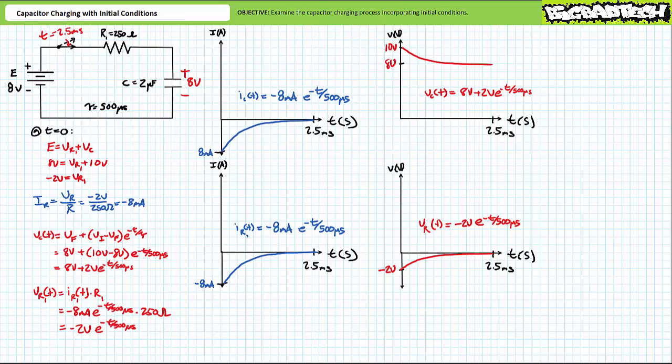Notably, capacitors resist sudden changes in voltage. In all of our examples, including those that had positive initial voltages, negative initial voltages, and even excess initial voltages, the voltage across the capacitor never underwent a disjointed instantaneous transition or a sudden reversal in polarity. That's the point. Capacitors resist sudden changes in voltage and are often employed in circuits that necessitate relatively steady or slowly changing voltage conditions. Also, it may be helpful to remind ourselves how the charge and discharge processes unfold.